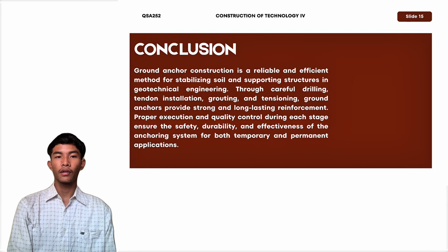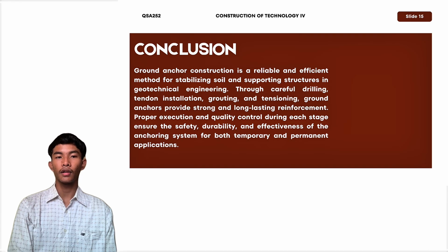In conclusion, ground anchor construction is a strong and reliable method for stabilizing soil in geotechnical projects. With proper steps like drilling, grouting, and tensioning, anchors offer long-term support. However, it is very important to maintain quality at every stage to ensure the safety and effectiveness of the anchoring system, whether it's for temporary or permanent use.